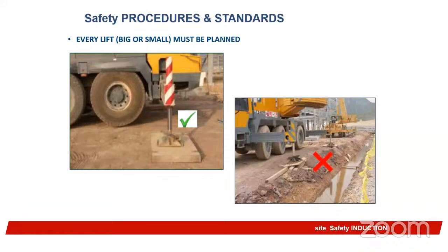If you have a generic person, maybe someone who's just walking around, then you talk about what to do when they see a lifting operation: not walking around the edge, or even within the premises, when a lifting operation is taking place. When there's a barricaded area for lifting operations, the person should not move under the lift, but find another alternative route. And also, when a lifting operation is taking place, you should be careful of objects that might fall at that point in time.